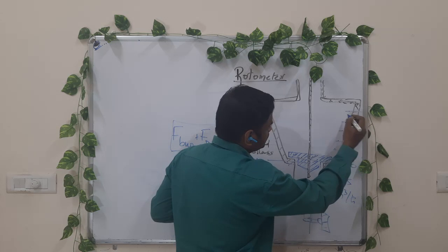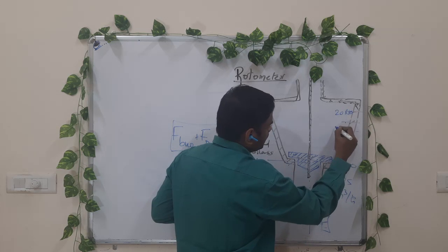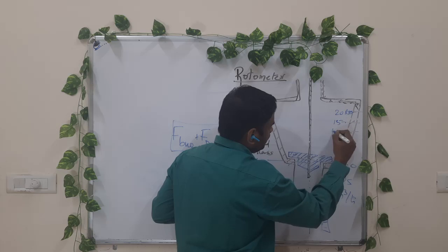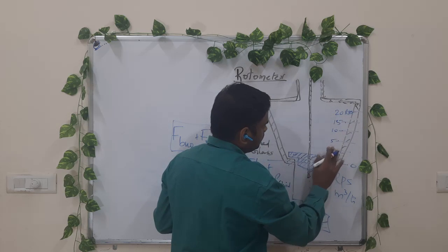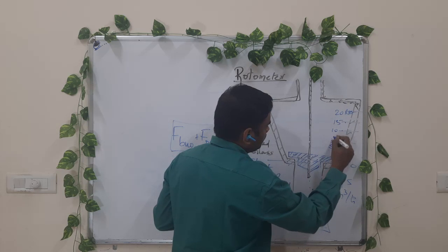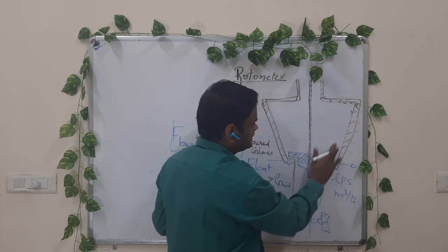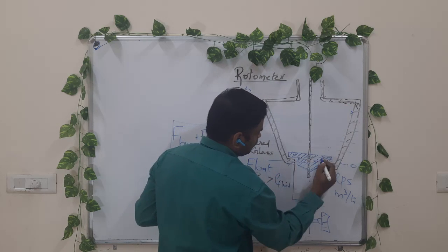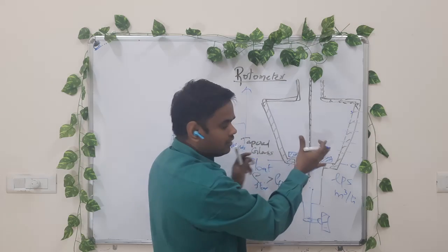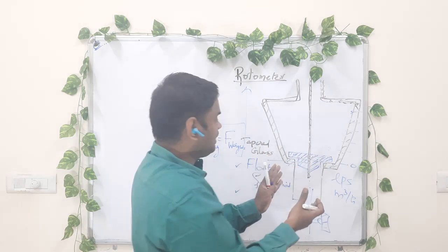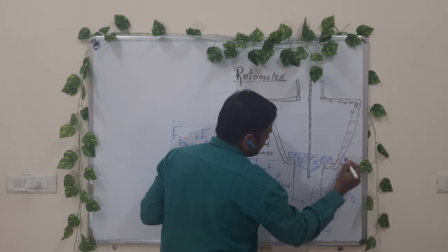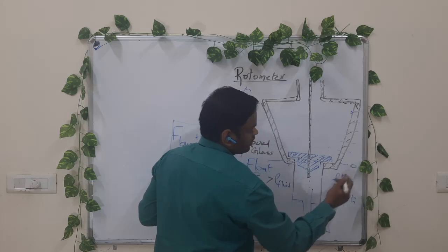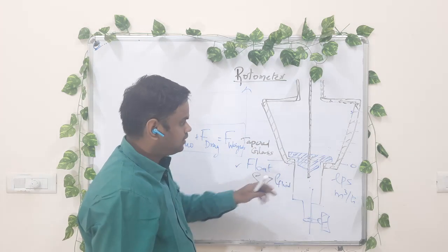The volumetric flow rate can be 0 to 20 liter per second. So you can have say 15, 10, 5, 2, 0 like that. Any scale should be in a proper scale, right? So 0, 5, 10, 15, 20 like that. We can have a scale. So we are going to have a calibrated scale, and this float is a visible plate, right? As I said, it's made of glass or plastic. So when the float takes a position, according to the float upper end, we can measure what is the liter per second or whatever unit the scale is calibrated in.